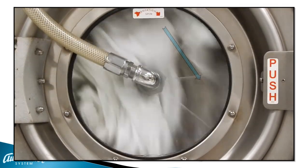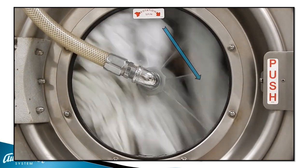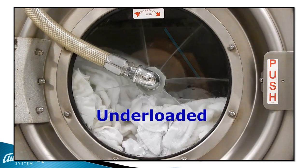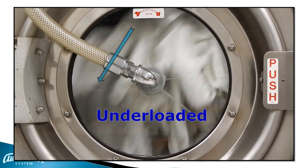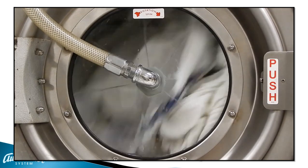So again, as we're looking at this washer right here, you can see we're about 12 o'clock to around 4 or 5 o'clock. What we're looking at here is an underloaded washer. It means we're wasting time, chemical, water, energy. They could be loading more in here to produce more linen at the end of the day.